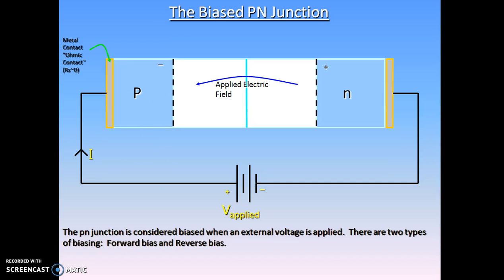In forward bias, the depletion region shrinks slightly in width. With this shrinking, the energy required for charge carriers to cross the depletion region decreases exponentially. Therefore, as the applied voltage increases, current starts to flow across the junction. The barrier potential of the diode is the voltage at which appreciable current starts to flow through the diode.